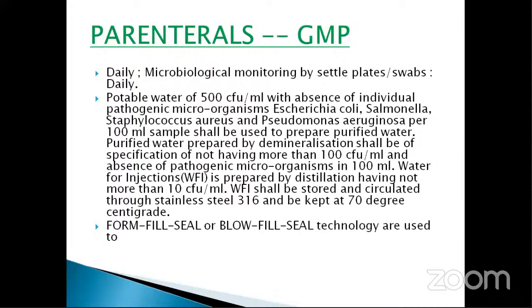How will you store this WFI in the manufactory? You have to keep it in circulation. That will be through stainless steel pipe, or in the tank that will also be made of 316 grade stainless steel, which is maintained in the GMP provision, not below that quality of stainless steel. And moreover, this WFI will always be maintained at 70 degrees centigrade, such that no organism can grow there, no bacteria.